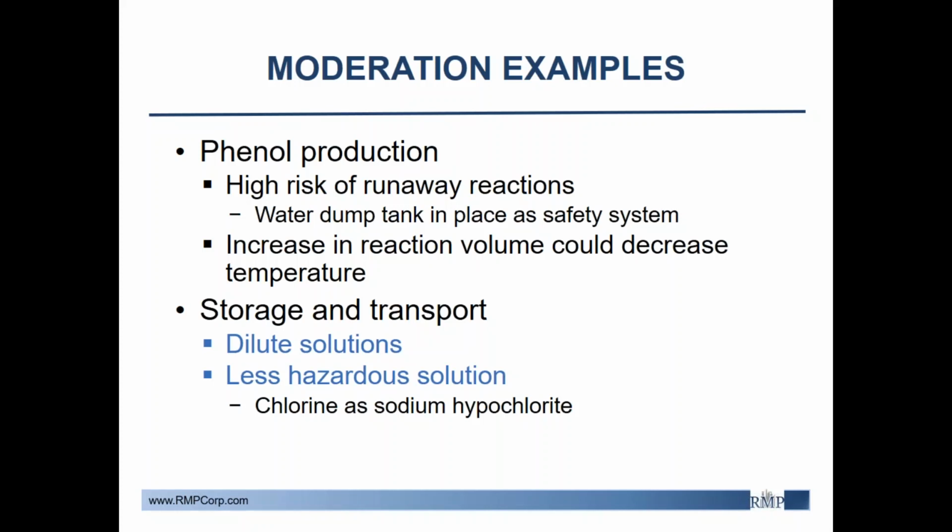Other examples include the storage and transport of hazardous materials. They should be stored as dilute solutions or in another form if possible. For example, chlorine can be stored as sodium hypochlorite. While sodium hypochlorite isn't exactly non-toxic, it's certainly less dangerous than pure chlorine.